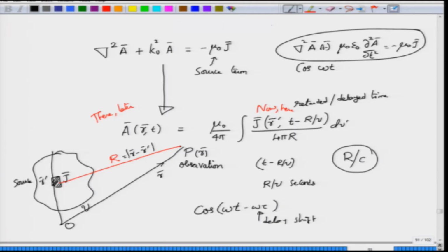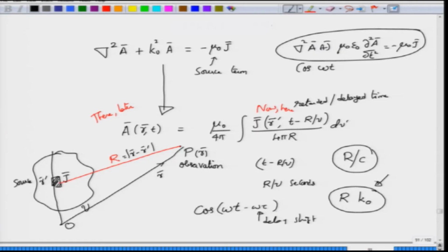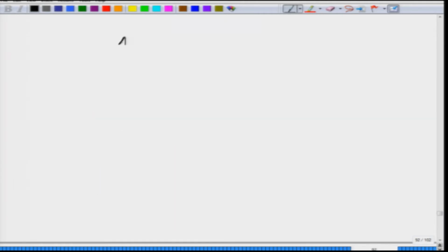Okay. So, we have already seen this, and we do remember that if I have a distance r and I know the propagation constant of the wave, then the overall phase shift that I would see is given by k0 r. Think of your transmission lines, your waveguides, even uniform plane waves; they would only tell you this, right. So, the phase delay would be k0 r, and I can convert every quantity in the time domain into the corresponding frequency or phasor domain, and then write A now as a function only of r. Please remember that we are working in the phasor domain, meaning that we have excited our current source with a frequency of omega, and that is what we are looking for.